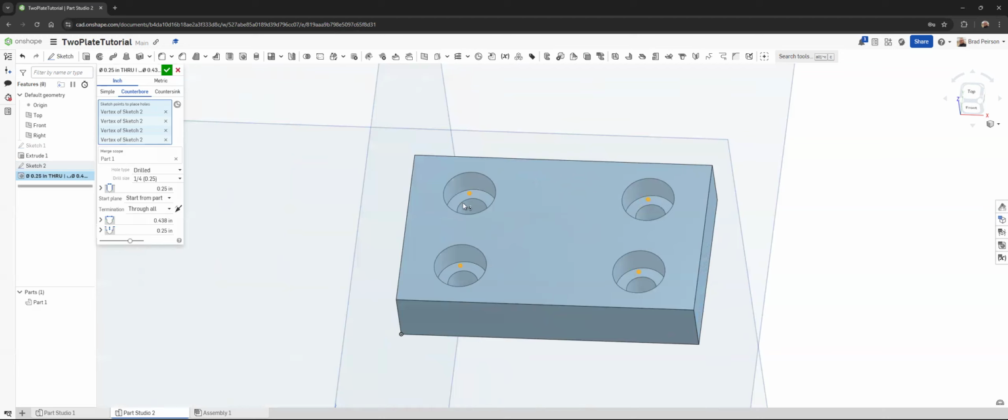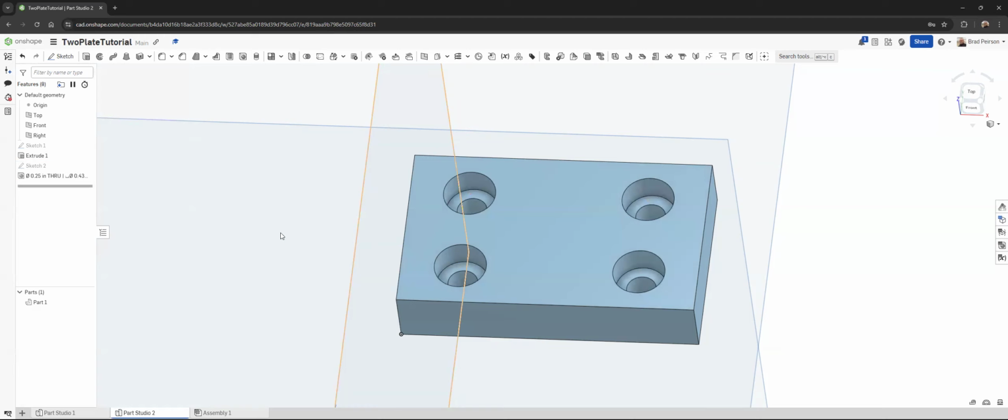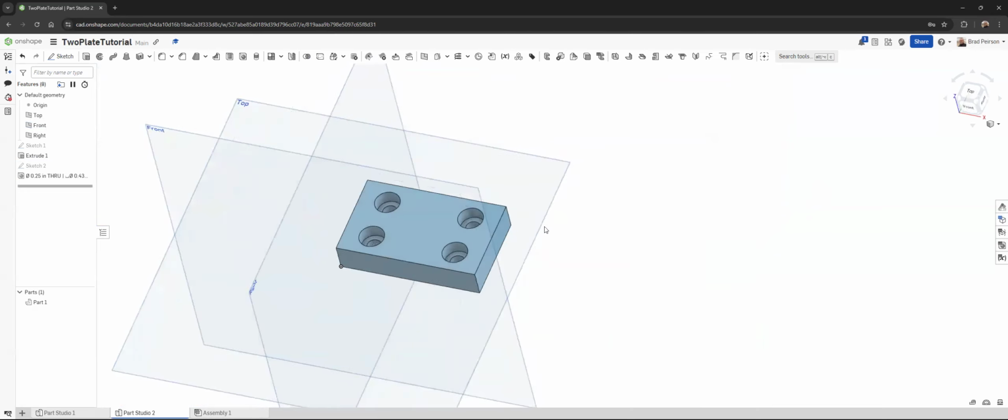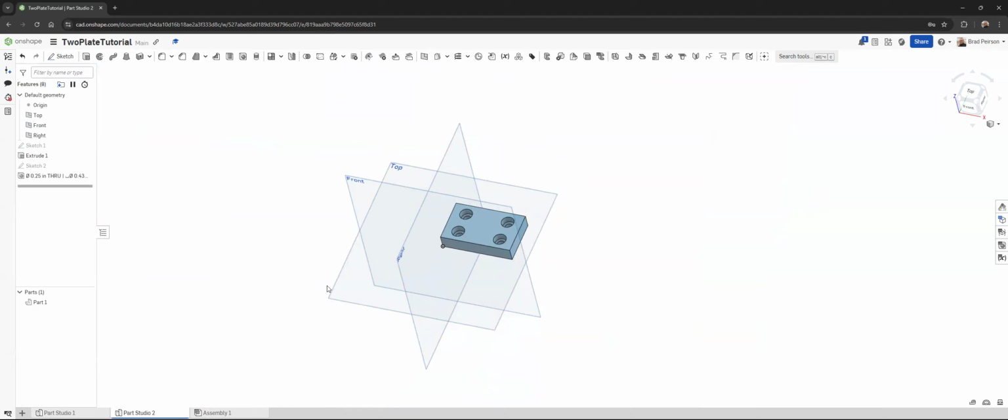Because again, in SolidWorks, in one of my previous videos, I mentioned they have a tendency to sort of undershoot the depth of a counterbore and a countersink so that things aren't actually below flush, the way we sort of like them to be. So that'll be interesting to see later. But for now, I'm going to accept this, and I've got 2 parts. Kind of cool. So far in the modeling, it's really just a workflow thing: do the sketching first instead of expecting to be able to create a sketch after creating the feature. But other than that, so far the functionality is almost identical to SolidWorks.